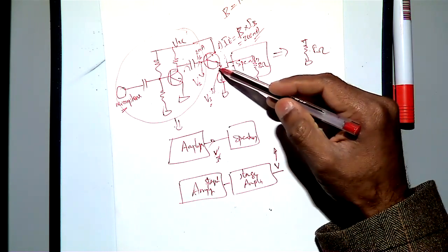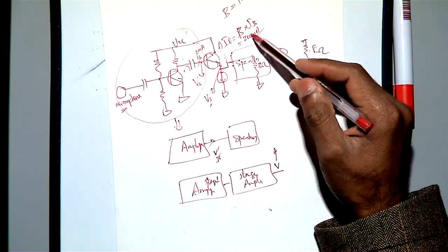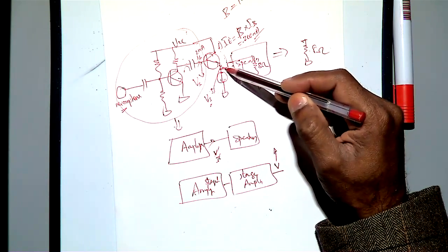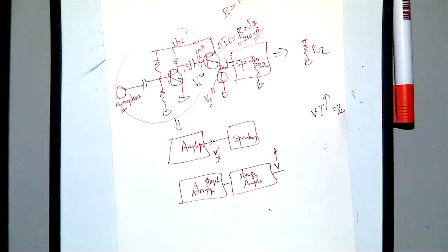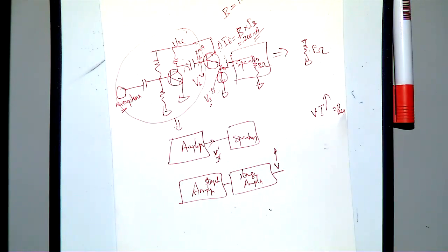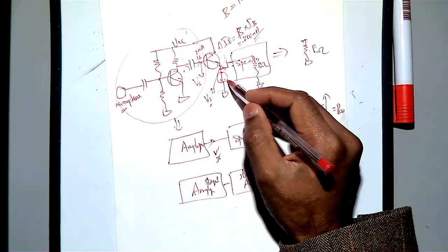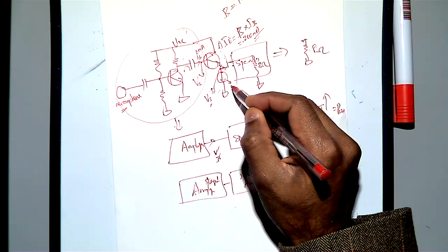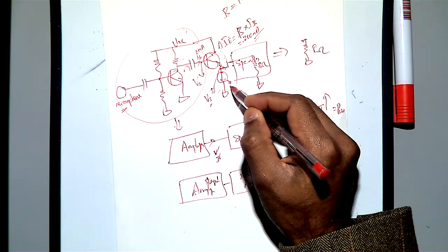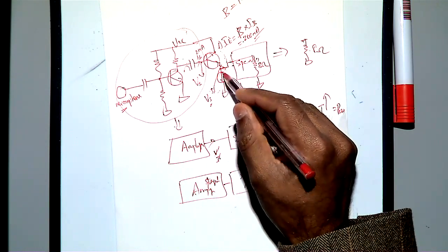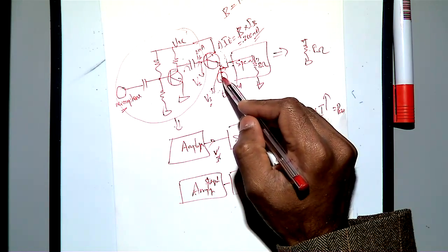And then you got the same voltage, but you have amplified the current so that you increase the power. So this is a power amplifier. But then a simple power amplifier is this one. But then the problem: when you are connecting a current source here, you will be biasing this current source, maybe for this case just 10 milliamps. Maybe you bias this current source for 10 milliamps, and then 10 milliamps emitter current will be flowing.